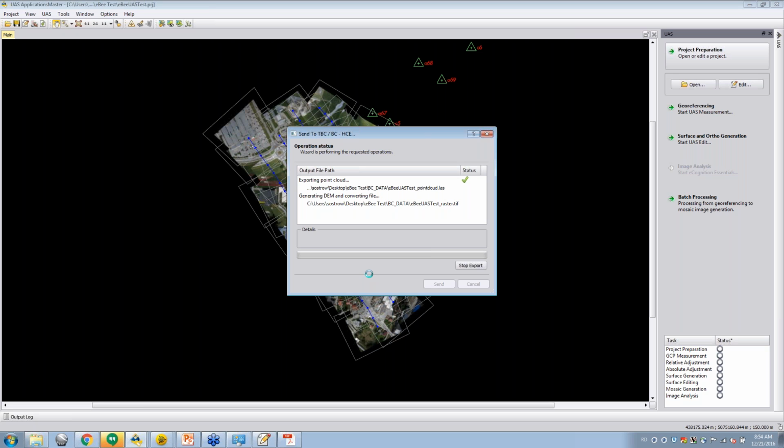Whether that's a field procedure or maybe for buildings, it really depends. If you want to improve your quality, you take more images over the area that'll improve your matching quality. Hopefully, with more images, you'll be able to match more points and more images, improving their accuracy. You then actually want to edit those elevations within TBC or within UASMaster, because usually large changes in elevation you can see in the point cloud aren't always accurate. It's a hard area for the software to estimate. So you would then edit the point cloud there so that you would get a better point cloud generated for that building.